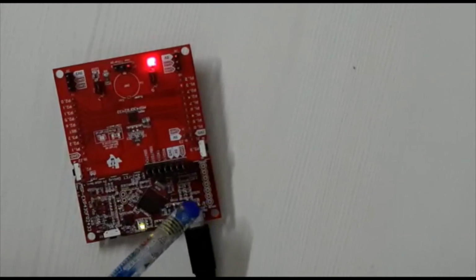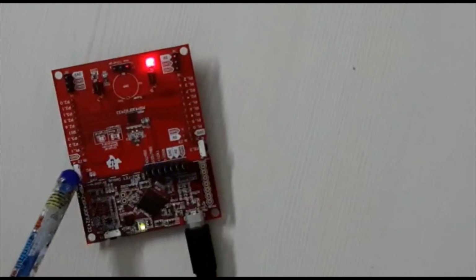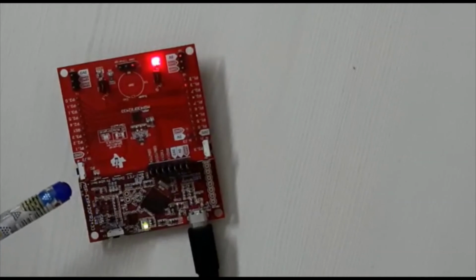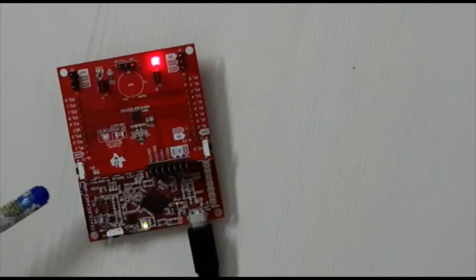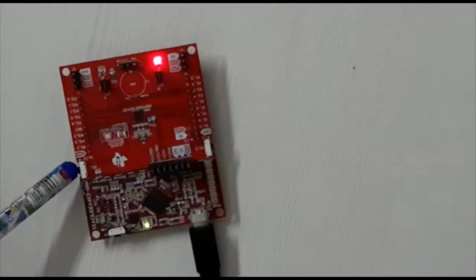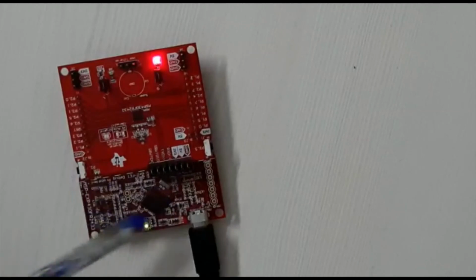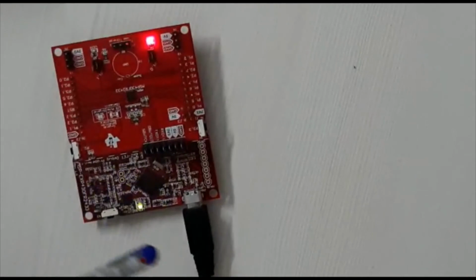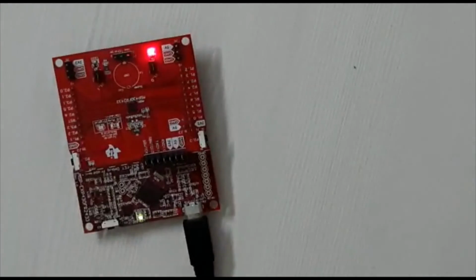Here one thing that we need to observe is that the CPU of this MSP430 microcontroller is constantly looking for this particular input, the P2.7 port. So that is in reality the reason why interrupts outperform polling: the CPU wastes a lot of processor cycles just monitoring the state of this input. Which is why there are more advanced versions, interrupt handlers, that we develop. Since this is a microcontroller and has a more primitive CPU, we can design a simple polling system instead. So that concludes our demo, and thank you.